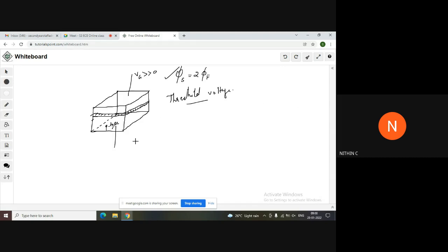So now we need to understand how we get to this threshold voltage. We represent it by VTH. Threshold voltage is nothing but the gate voltage itself. The gate voltage we apply, at which strong inversion onsets, that particular gate voltage is called the threshold voltage. So it can be written as VTH is equal to this gate voltage being dropped across the oxide layer and across the semiconductor.